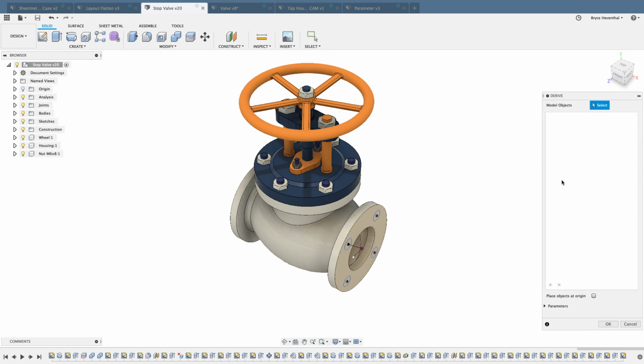So you see this dialog over here is basically what I'm going to pull in. Typically, when we use the insert component from the data panel, you grabbed everything in that Fusion 360 design. So if I were to do this with this design, all this valve would come in, this top piece would come in, everything would come in, and maybe I just want this handle right here.